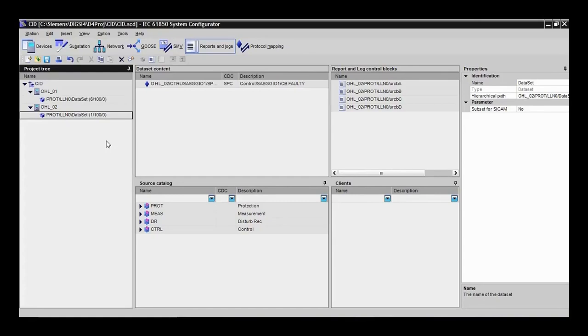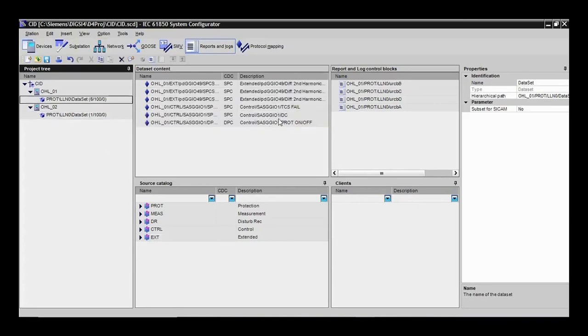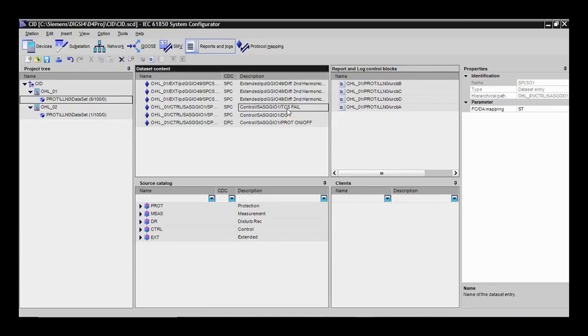Why? Because this is considered a generic signal. What does that mean? It means you created it in the first place. You didn't take the signal directly. You took the signal as a generic signal, and this generic signal is what you defined here. So why is it that someone doesn't understand that this is a binary input number 1? He understands that this signal is a generic signal, and you named it trip circuit supervision somewhere. Therefore, you copied and pasted from the generic signal and placed it in another relay. In the other relay, this generic signal already has a different name, so it automatically took it.